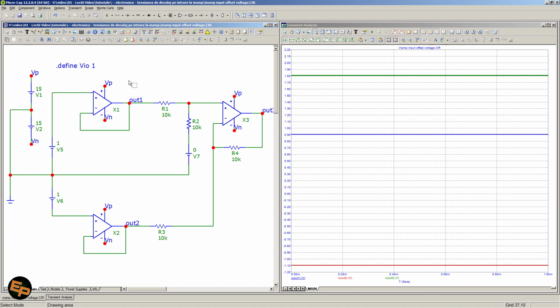Whatever, let's just skip over this detail, because it doesn't matter. So we have minus 0.1 volts of differential voltage for all of these three op-amps. As a result, on the positive side, the buffer, instead of giving us plus 1 volt on the output, gives us 0.9, right?